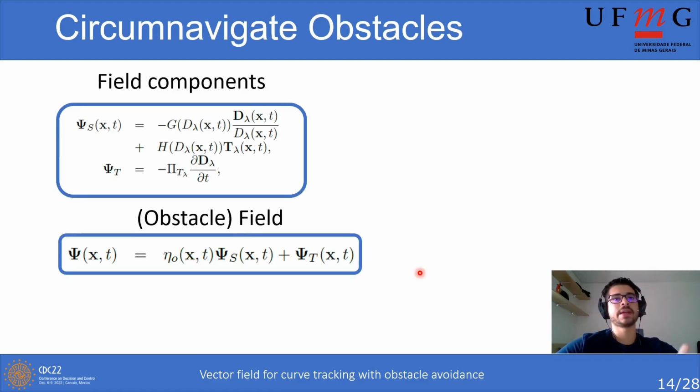From there, the approach keeps following the curve field method. We find a unit field to follow static obstacles and the feed forward gain, and we sum them using a gain to the static field to assure constant norm. And thus we have the final field to follow obstacles. Let me call it obstacle field.